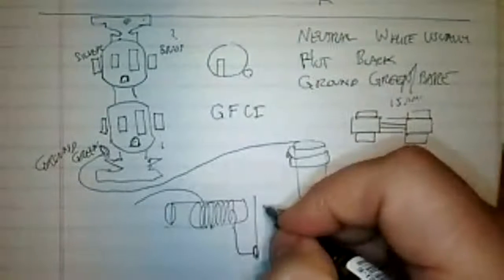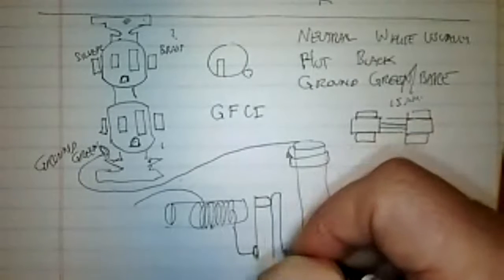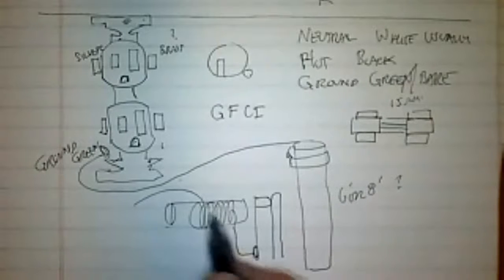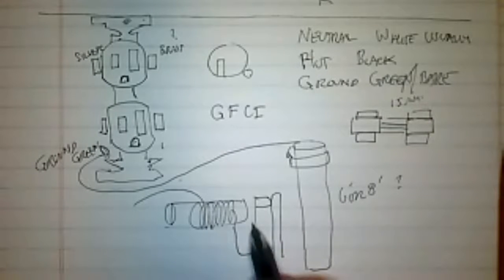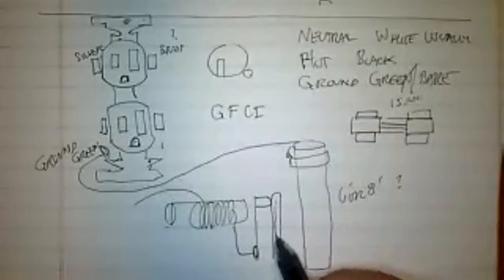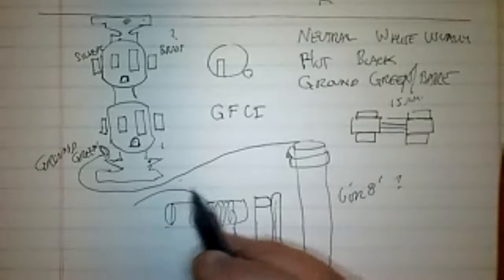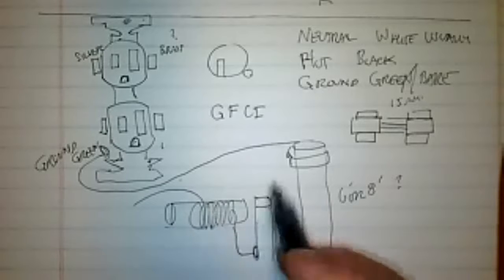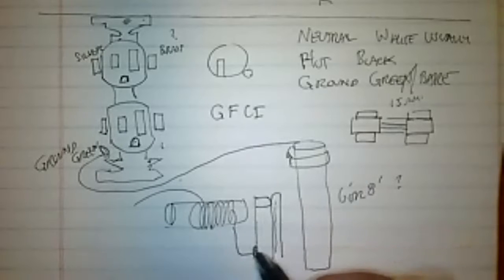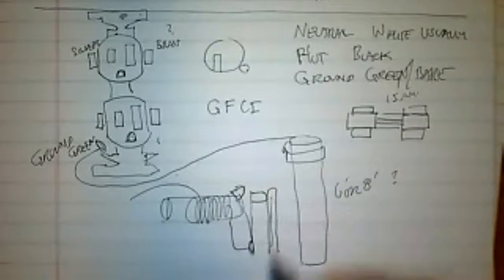And then let's say this thing is touching this metal part right here. So all the current's supposed to go around this magnet, along this metal bar, through that little metal plug, and then touch this, and then go out to the house. However, if this current surges a lot, that's going to make this magnet really strong, and it's going to bend this flap. So this flap goes over like that, and it disconnects the circuit. Does that make sense? So that's how those things work.